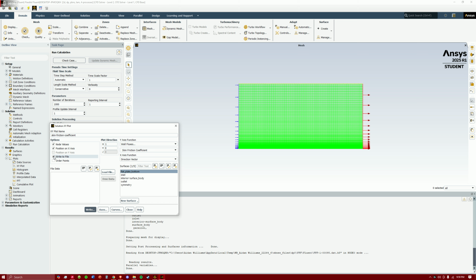Then you can open that in either text or Excel, but do note that the x-axis and the y-axis are shifted or something like that. I don't know how to say it. You could just highlight both the columns in one highlight, and then in Excel, just filter from smallest to largest. It won't mix up your X and Y's. They stay together. I don't know why. That's just how ANSYS saves files.